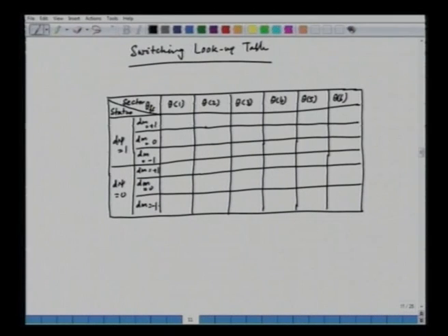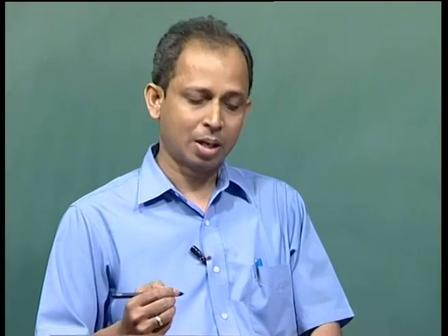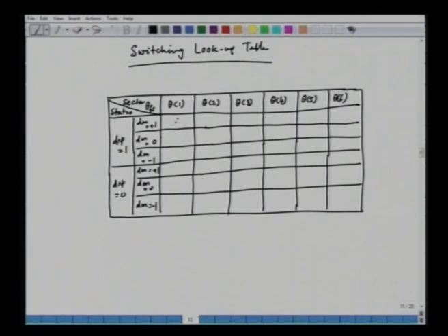So we have to select a suitable voltage vector so as to fulfill the torque status and the flux status simultaneously. Say for example, if we concentrate on the first element of this lookup table, we have d psi equal to 1 and dm equal to +1. It means we have to increase both the flux and the torque. So we apply here a voltage vector, that is V2.